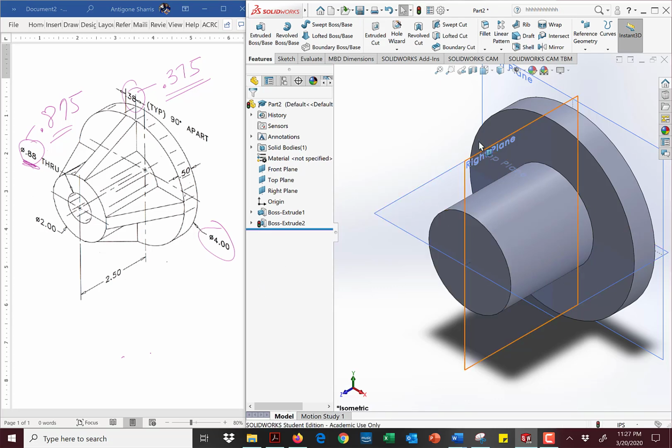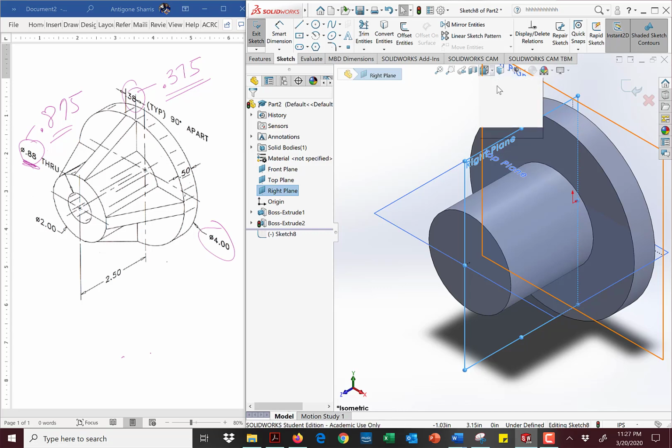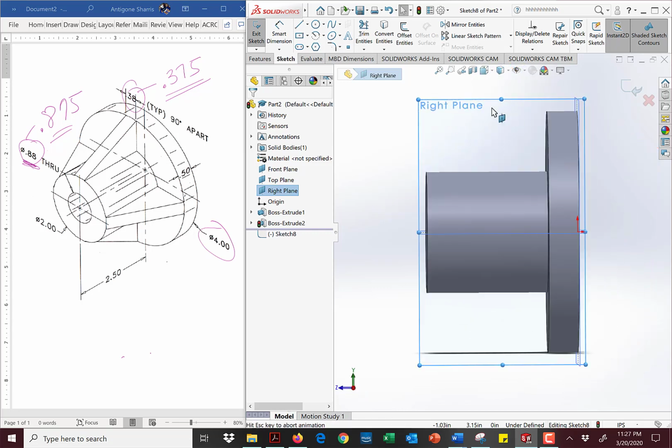Let's let it be. So if I can't put a rib in using the rib command, I went through all that gymnastics just to show you that you cannot use the rib command. How do you put that rib in? Well, you old school it, as I like to say. You create the shape and you extrude it. So we go back into that view. We're going to go ahead and go normal to.